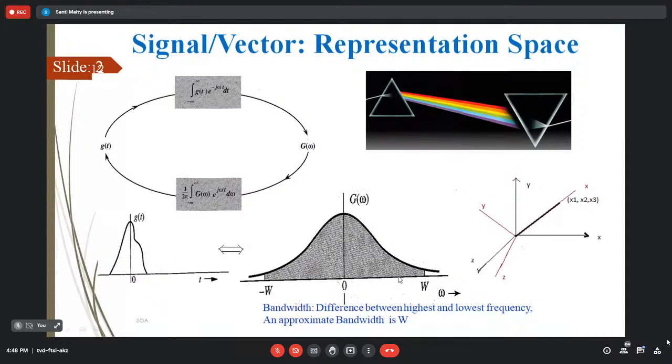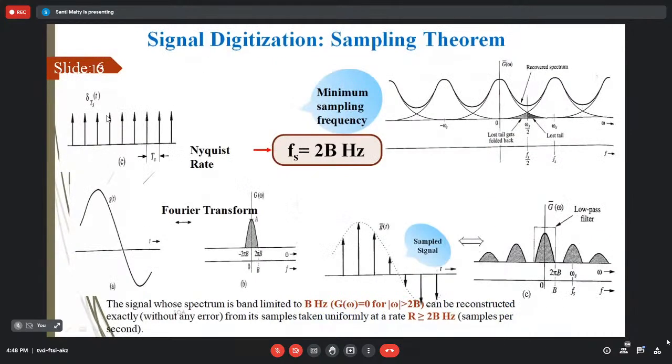If your signal is band limited to W, and you follow this sampling rate, with this time interval between sampling instants, then you can reconstruct that signal. What was your concern? That if these are the values available, can I reconstruct the signal? Can I go back from this discrete set to the original? That was the issue.